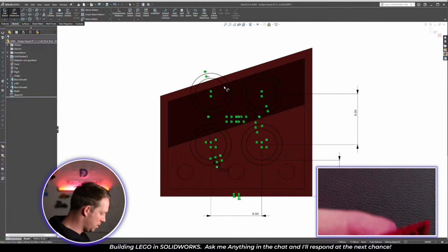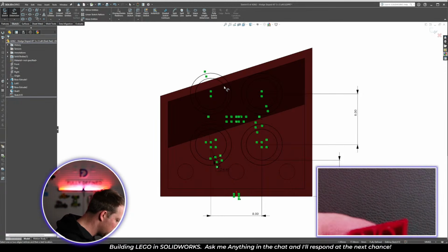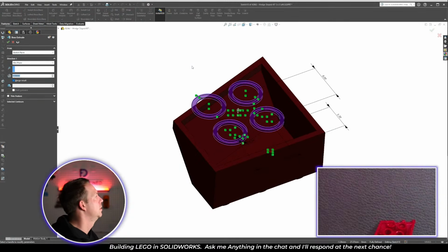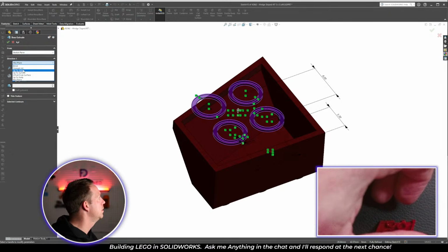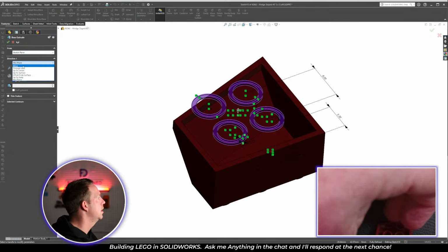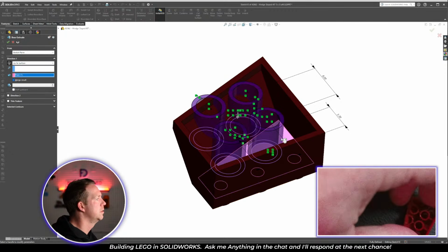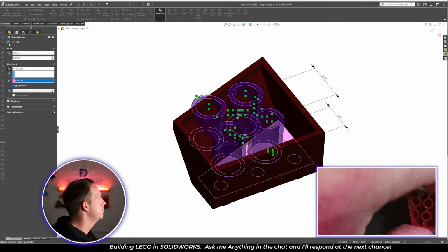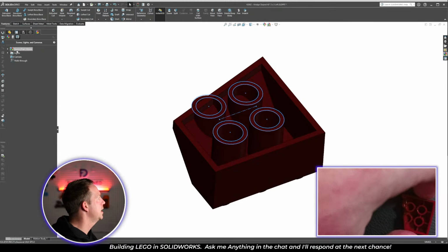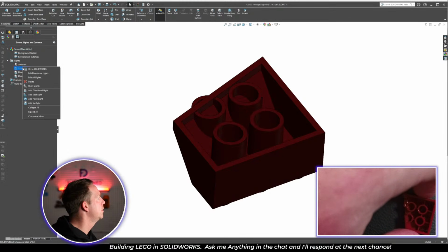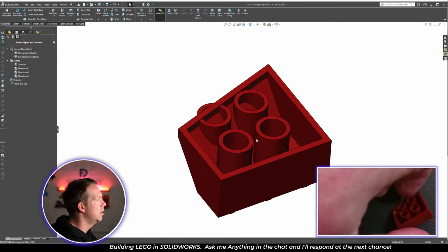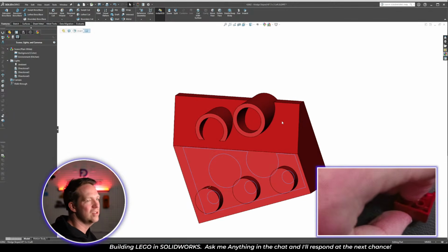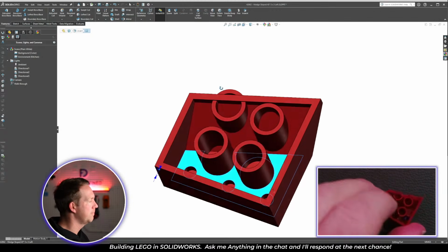All right, we can see that one on the top edge that's getting cut off. I'm going to ignore that for now. What I'm going to do, I'll do the extrude and then we'll see what happens. So I'm going to go up to surface, and I'm going to offset it 0.2 of a millimeter down. And I'll just change the colors a little bit so you can see a bit better. I'll turn this one on. There we go. All right, so by going to this surface at the very bottom, it means these parts pop through on the outside. I don't really want that detail happening.